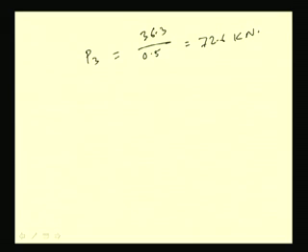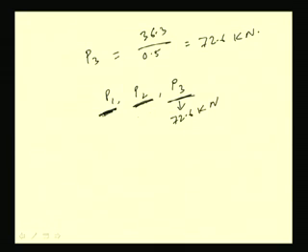So, for 3 types of joint, 3 allowable loads we have derived, P1, P2 and P3. P1 we have got from the connection between girder and angle, P2 the permissible load due to the connection between angle and bracket, and P3 is the permissible load due to connection between bracket and column. In P3 we are getting 72.6 kilonewton, P2 we are getting 185.9 kilonewton, and P1 we are getting 217.8 kilonewton.